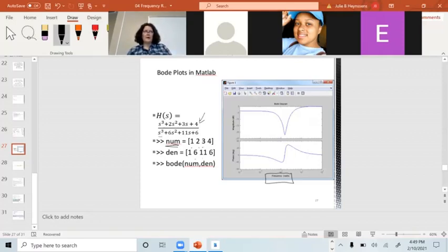So when you get into lab at some point, you'll go, this Bode plot's perfect, but it's off by a factor of about 6. So they both look the same. Same shape, but the scale down on the bottom will be different. This is a good way of checking your homework, because you can go through, given the function, do a quick plot of it, and you know what you expect it to look like. And I'm sorry about the homework.